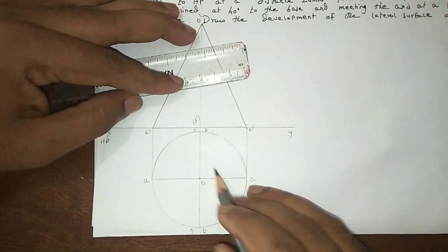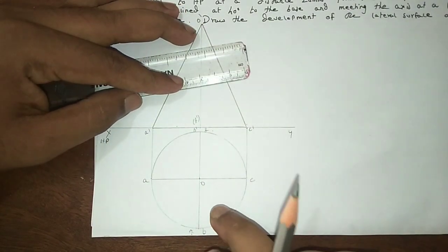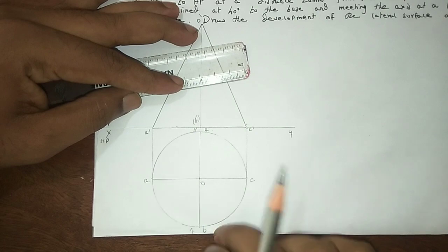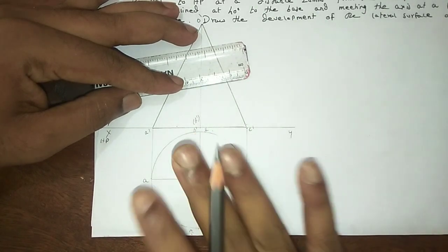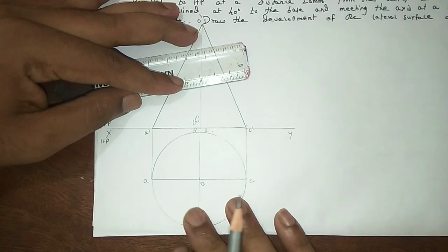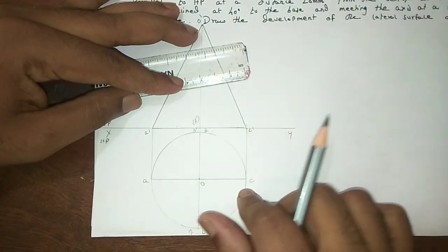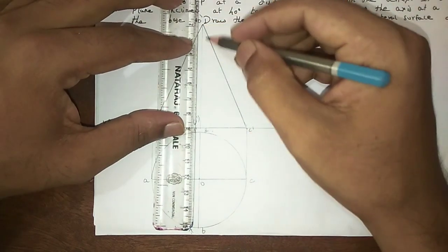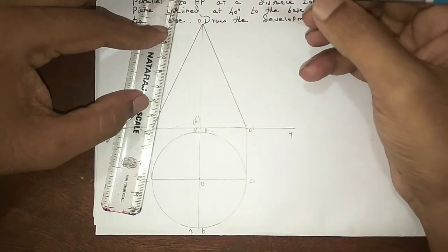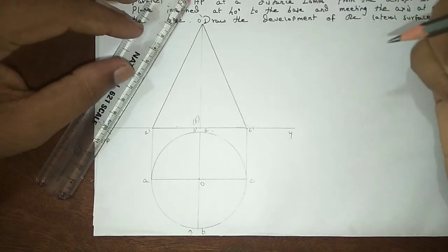And also the bottom circle we divide into 4 equal parts. These lines are not slanting edges; actually it has only generators. For our convenience we divide this circle into 4 equal parts. So in the center you draw a very thin line, the axis line. Now the symbol positioning is completed.